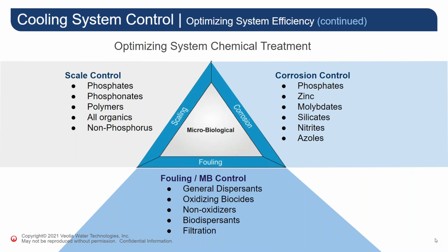Fouling can occur from dirt and debris, from corrosion byproducts, from dissolved solids, and from microbiological activity. Not only does fouling reduce flow through a pipe, it also provides a place for corrosion to occur and a place for Legionella to grow. The cooling tower itself acts like a giant air washer, so whatever is in the air will end up in the tower water.